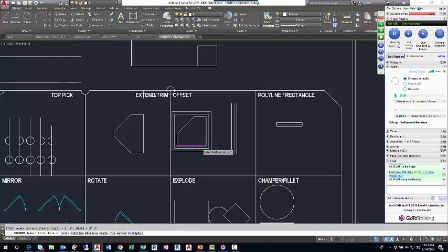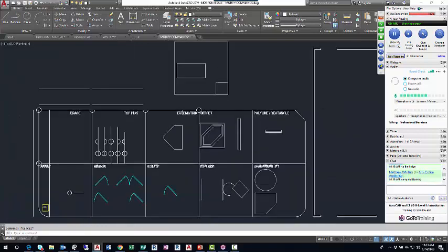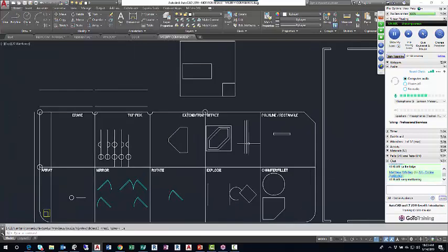I could do the bottom right corner, like so. So I'm just kind of doodling chamfer, chamfer. Oops, missed it. There we go. Okay. So questions on, what was that? Offset, explode, fillet, chamfer, those 4 modify commands. Questions at all?